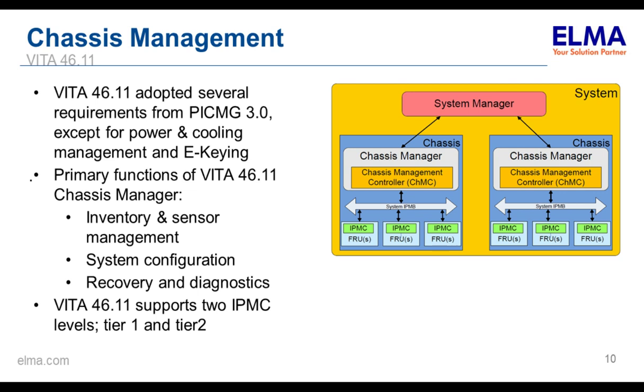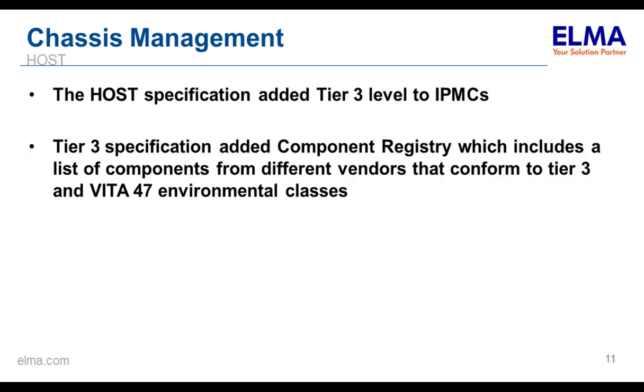VITA 46.11 also supports 2 levels of IPMC, which would be Tier 1 and Tier 2. And the HOST specification also added a Tier 3 level to the IPMCs. The Tier 3 specification from HOST adds component registration or registry information that would list all the components from the different vendors that conform to Tier 3 and to the VITA 47 environmental classes.